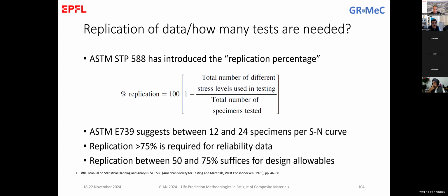So this is, again, a kind of guideline, and we know now that you cannot build a nice, reliable SN curve without having at least 12, 15 data points. So this is experience that tells you, okay, my test is okay, even if I'm not following religiously these recommendations of the standards.